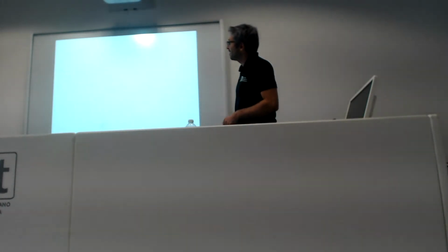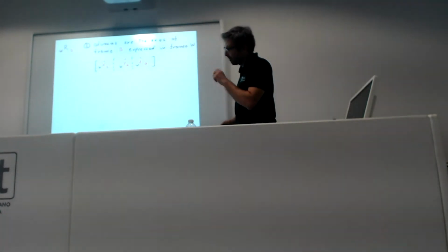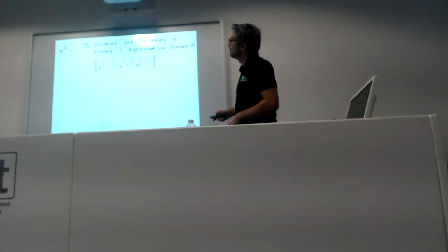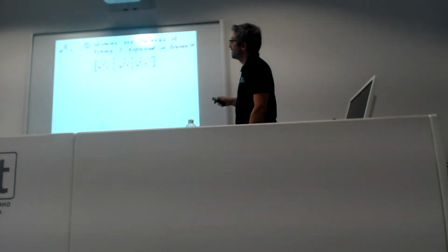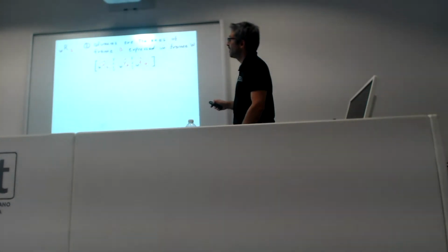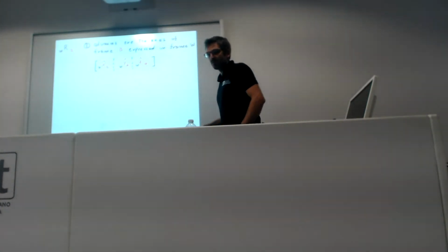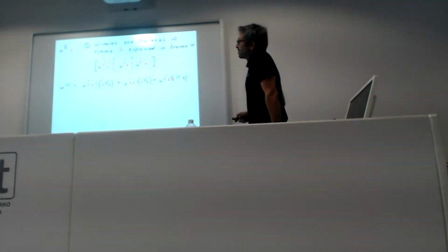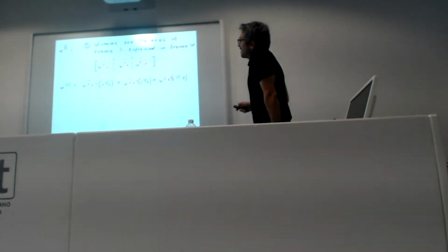While if you flip these two, you can say that the columns of the matrix are the axes of the base frame, again expressed in the world frame. So if you flip the addends, you just flip the rows with the columns. And this makes sense. Let's verify. Yes, because the output should be a vector in the world frame.